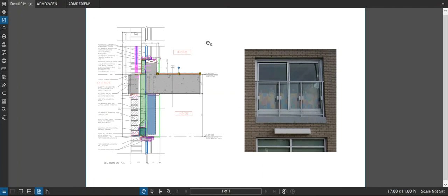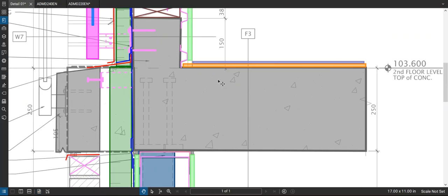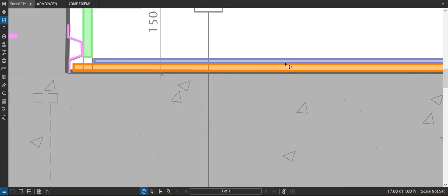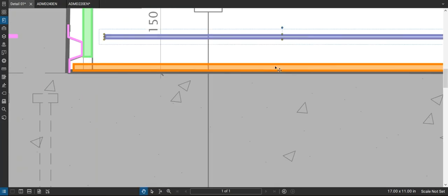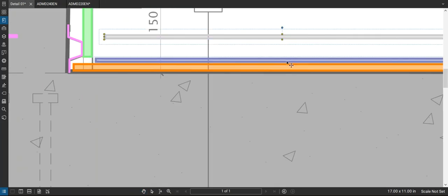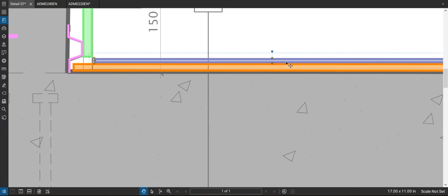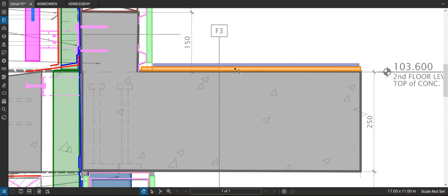Okay, so something else missing here is, this is a condo building, so an apartment building. So at the very, very least, you'd have an acoustic mat put down there. Those come in various thicknesses and different types of products, but a cork board type thing, maybe 13 millimeters thick. And then you put on whatever your floor finish is. Of course, you can keep adding layers to get better acoustic value, but that'd be the standard, I guess, absolute minimum in a concrete structure.